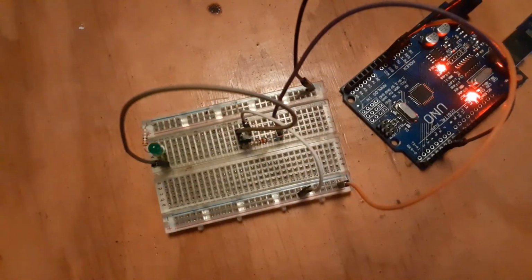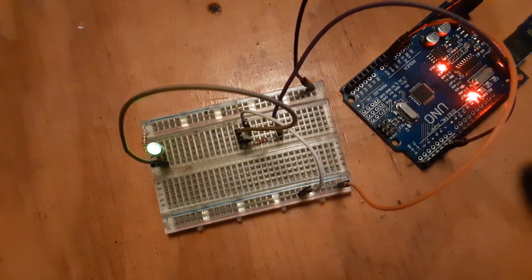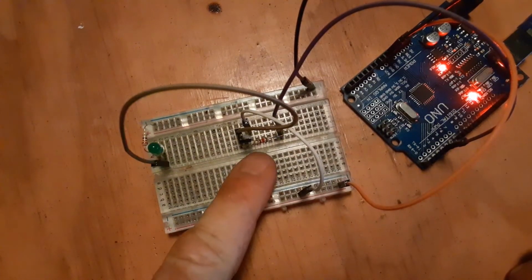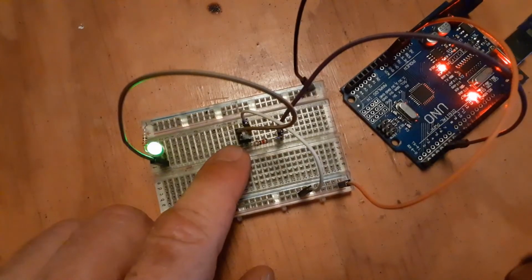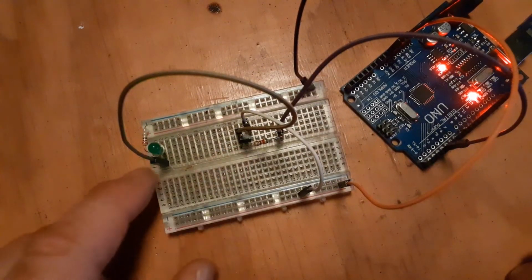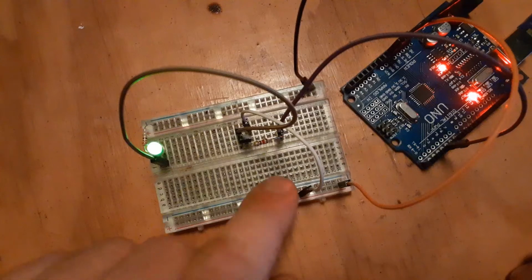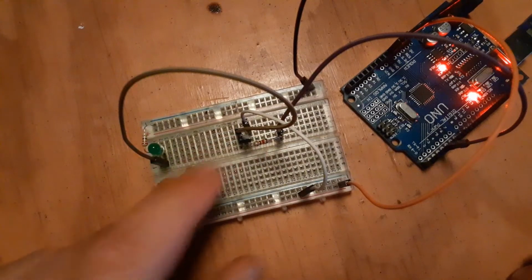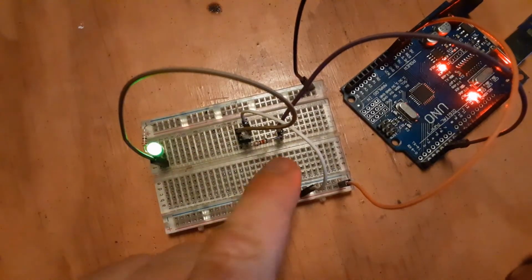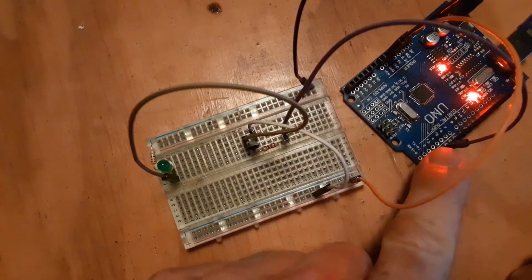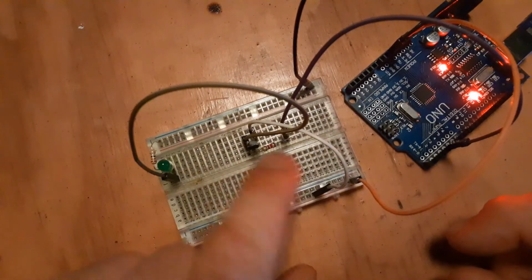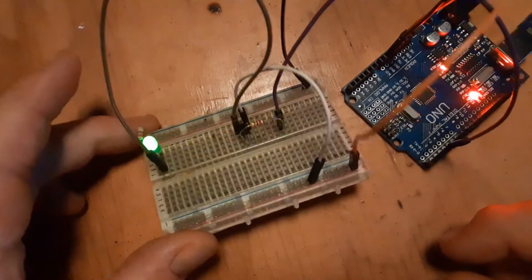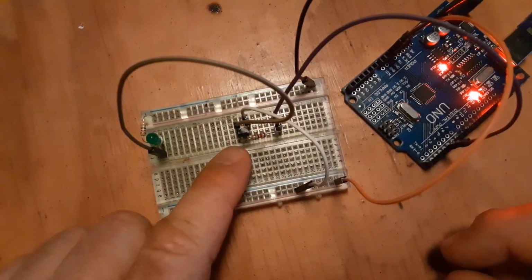So when I bring power to the circuit here, you can see that it just turns it on and off. Whenever the Arduino writes that pin high, writes a 1 to the pin, turns this signal on, it flows through the transistor, turns it on, and the power is able to flow from the voltage source through the transistor, through the LED, and back to ground. And when the signal from the Arduino turns off, the power can no longer flow through there. So just flipping the switch, but you can see it's still just turning the light on and off.